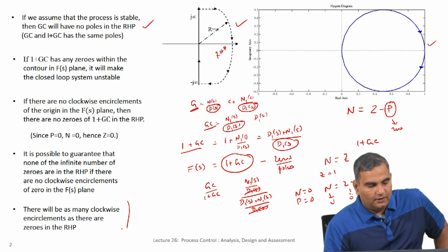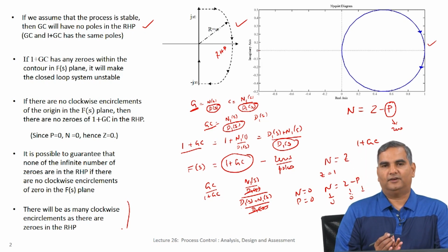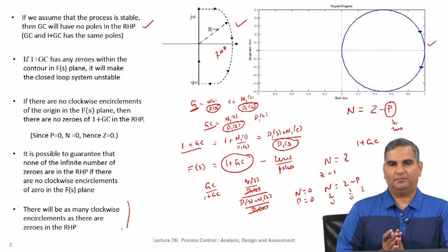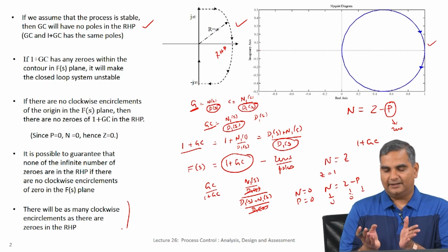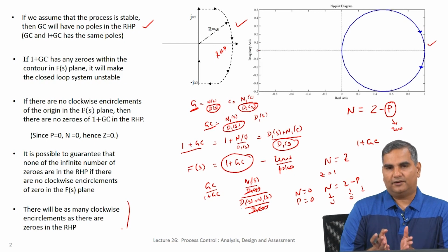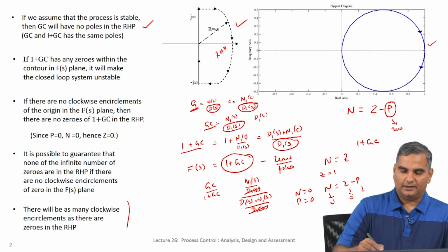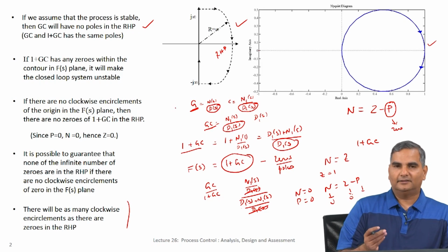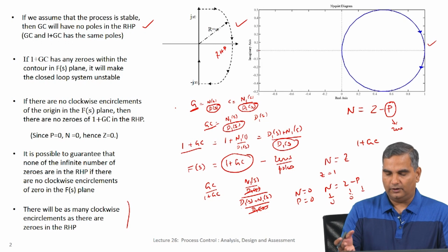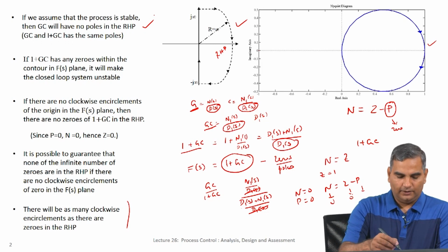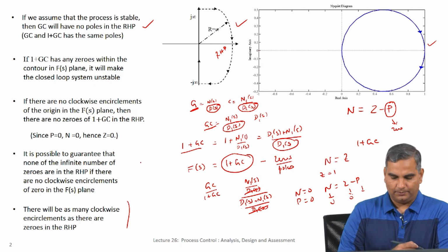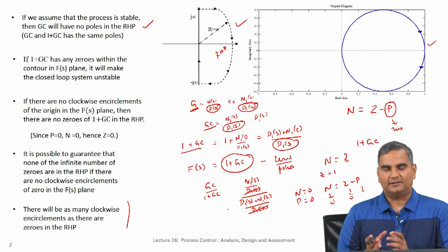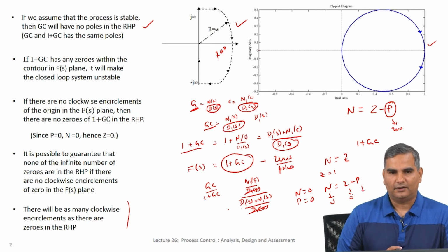So, that is how this whole idea of Nyquist stability is translated to time delay systems, and it translates to time delay systems because F of s can be any functional form. I need to simply compute the F of s value as I go through this contour, and this is done using software, and you will have these plots which we have to interpret. So, if you understand each one of these points clearly, then you understand how to use these Nyquist plots for stability.